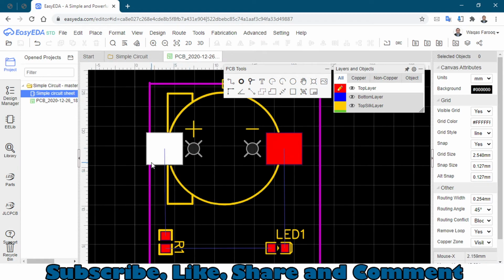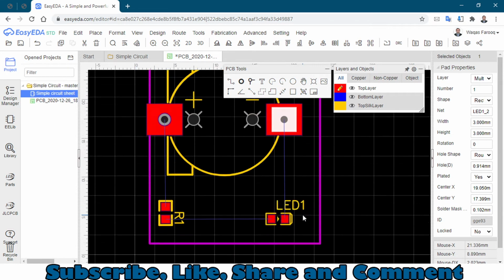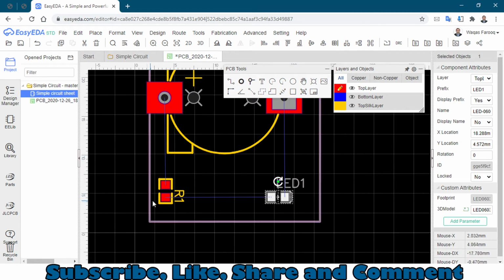Let me just zoom in. Here we have two pairs of this battery and these resistors and this LED. So I will place this pad right here and one right here for soldering, and you can also make them, these are rounded shape, you can also make them rectangular right from here. You can also change its width, like it's 3.0 mm, and I will change it to 3.0, and you can make it rectangular or circular shape, whatever you like. And now we have this LED and this resistor.